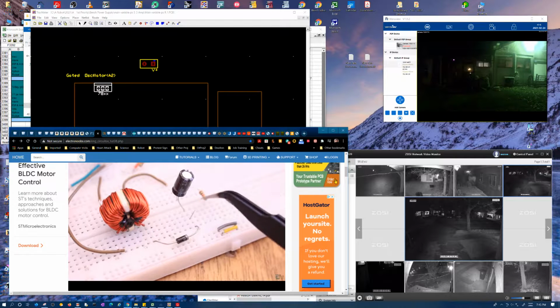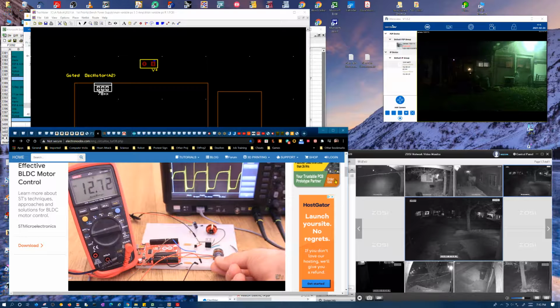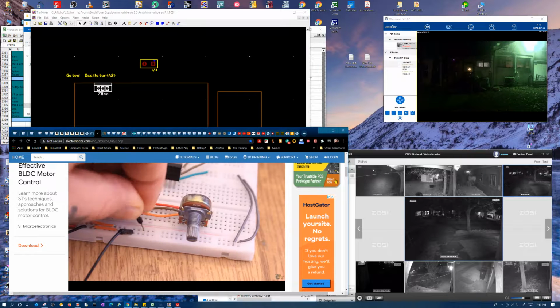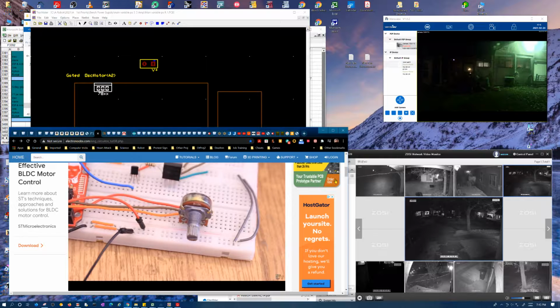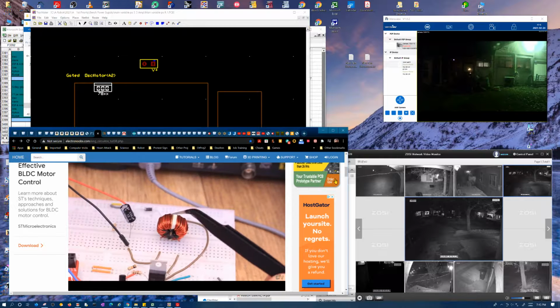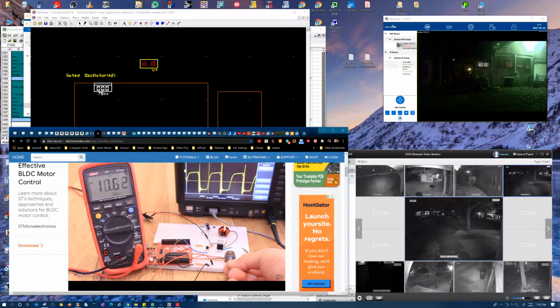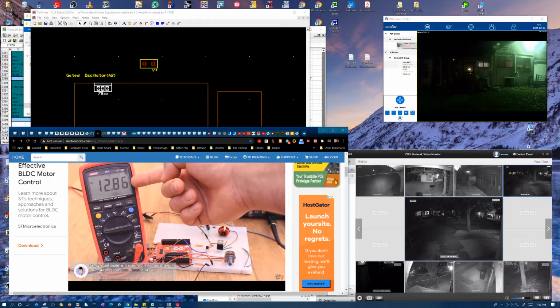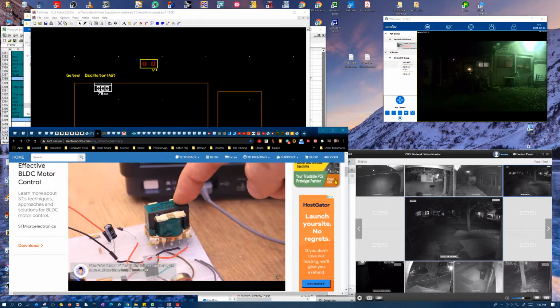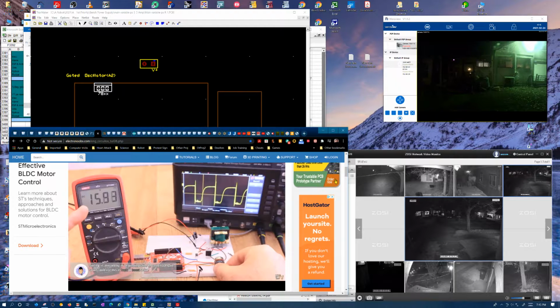And as we have seen before, we can regulate the output voltage. I have 12 volts connected at the input. The inductor in this case is a 1-to-1 ratio. That's why the output voltage will only go from the input value to lower values. But now I have this other transformer with bigger ratios. As you can see now, with the same 12 volts input, I could now reach voltages up to 20 volts.